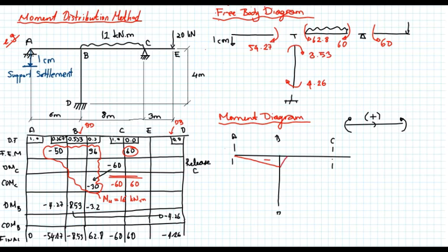So we see a parabolic variation, minus, plus, minus, and the linear variation at the cantilever, minus. Of course, these 2 points are not at the same point, so I have to be careful while doing that because they don't go to the same moment value. So let's draw it this way, minus, and the moment for member BD can be drawn as follows.